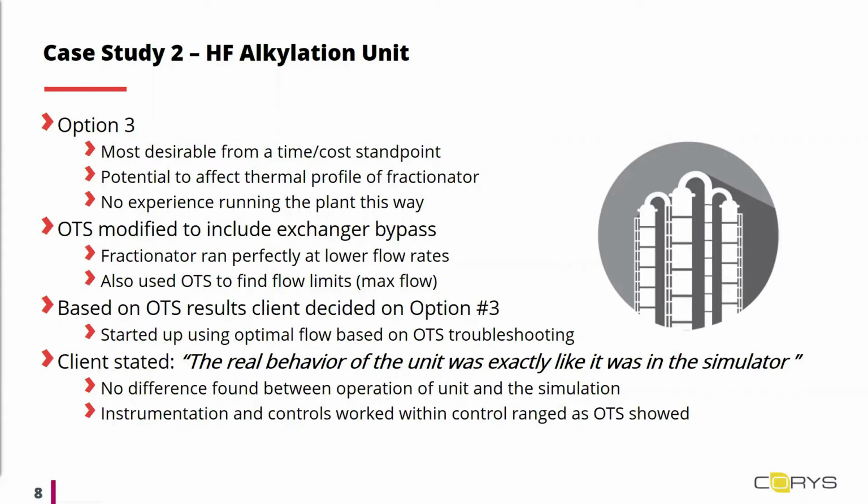However, the client had no experience operating the plant this way and did not know how the thermal profile of the fractionator would be affected. And the technology licensor could not contribute to the decision as they did not know how the operation would be affected either. So they decided to test it out on the simulator on their OTS. So a standard malfunction of the simulator was used by inputting a 100% fouling of the heat exchanger to mimic a bypass with no heat transfer.